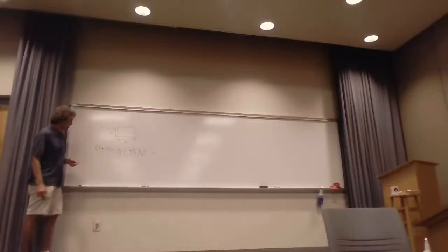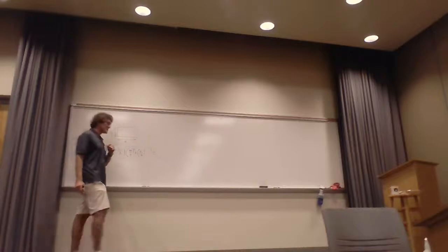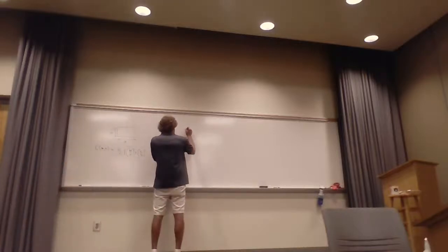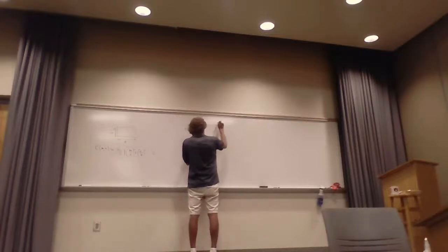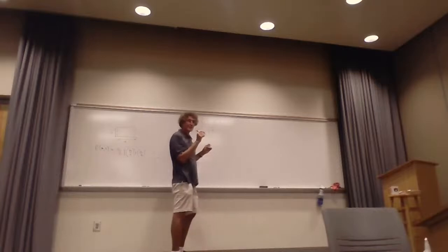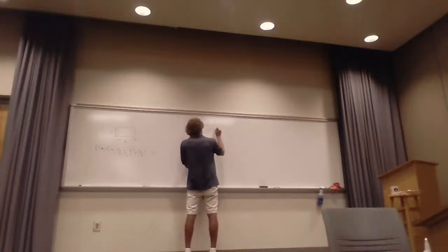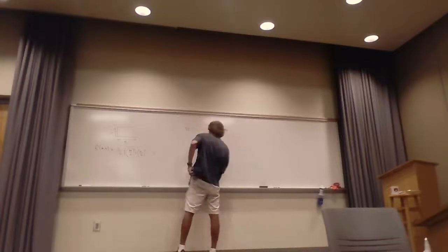And here you go through and you find out the first frequency that you're going to get will be the TE10 frequency, right? And that has a cutoff frequency of 6 point something. I forgot exactly. 6.6. 6.6, yeah. I said 6.56. 6.56, that's fine. 6.56 gigahertz, right? Yeah. That's the first frequency.